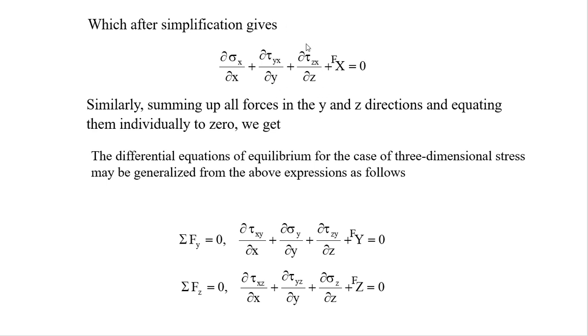Similarly, we solve for the other two directions by using the other two force equilibrium equations, summation of forces in y direction and z direction. We can get the other equilibrium differential equations. These three equations are called the three-dimensional differential equations of equilibrium.